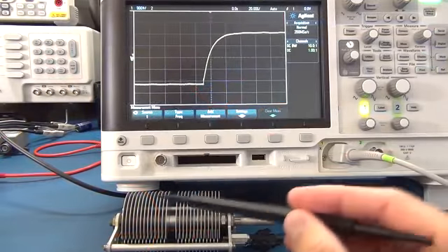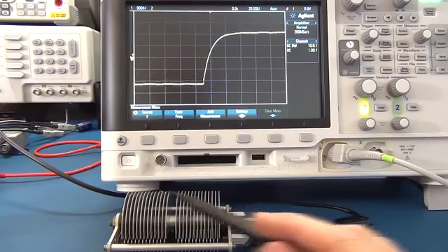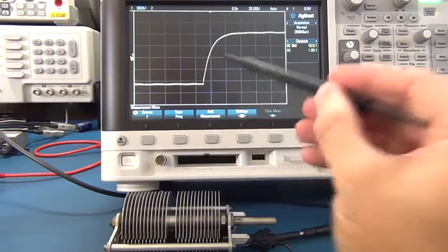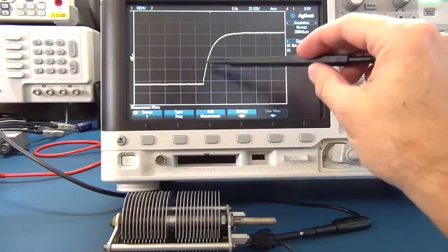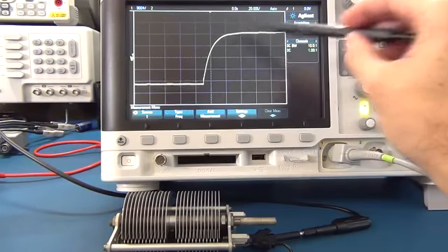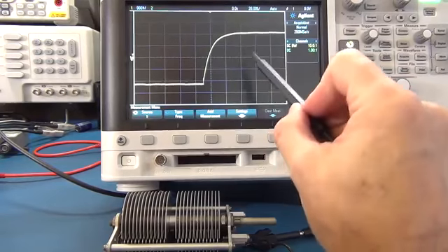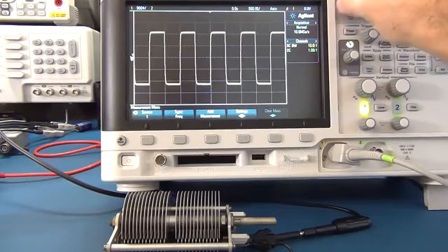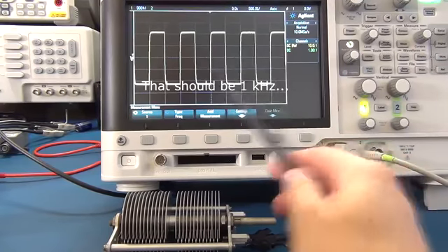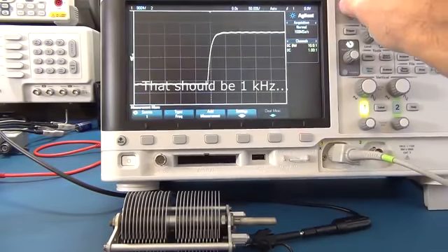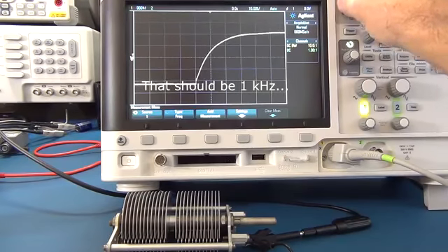Right, so I've got everything set up. Obviously the variable capacitor is here. We've got the Agilent oscilloscope, and on here I've set up and dialed in this nice charge wave. Now remember, this is an AC wave, so if I draw out, we'll actually see there are multiple waveforms because we've got an AC signal going in here at 100 kilohertz. Obviously we want to get in so we can see the wave.